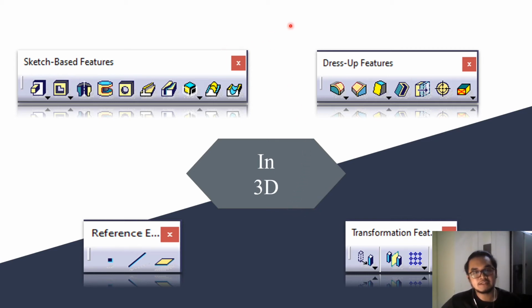Okay, for the next slide, I'm going to explain about the tools in the 3D section. In this section, for the first tab named sketch based features, we use the tab icon, pocket icon, shaft icon, groove icon, and the slot icon. For the second tab named dress up features, we use edge fillet here and the shell. For the third tab named reference elements, we use this point and plane icon. For the fourth tab named transformation features, we use this mirror icon, which is similar to the one in sketch, but as I said, it's for 3D.